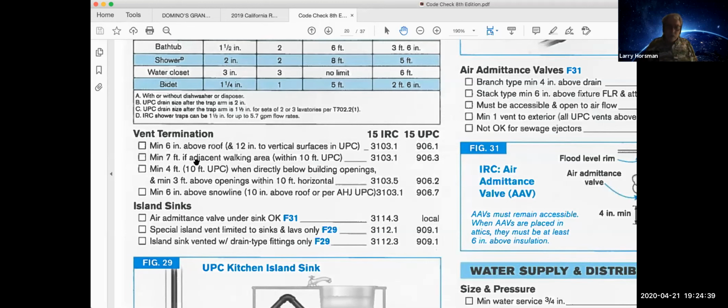It's only running partially full. The sulfuric acid in vapor form is up there and it attacks the top of the pipe and will eat it away. Clay pipe is good for that because the clay, when they fire it, vitrifies or forms a glass lining. And the glass is more or less impervious to most acids, not all acids, but most acids.